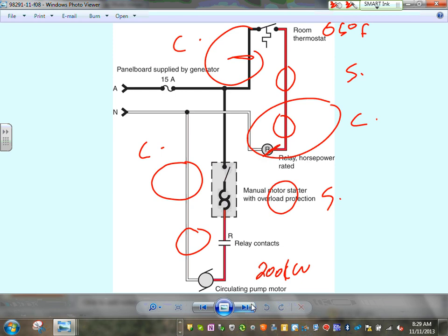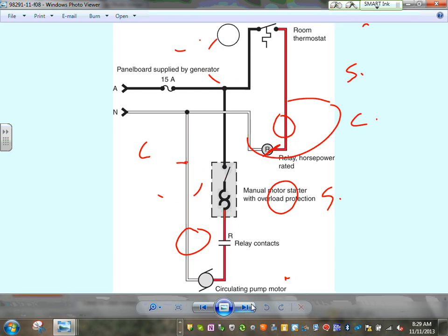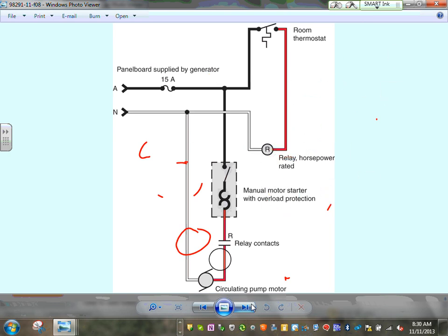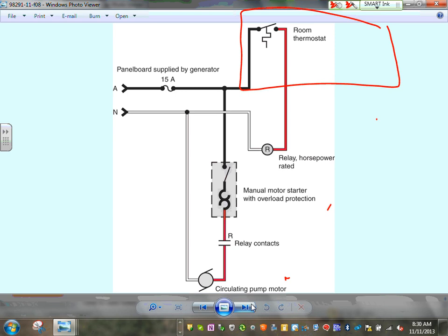We talked about the boiler, the thermostat. This is my generator panel. This happened to have a room thermostat. Now this is your office, Adam, calling for heat. Look what happened. So here's Adam's office right here, calling for heat. And now when this is closed, look what happened. The relay is energized, guys. It will close this contact.